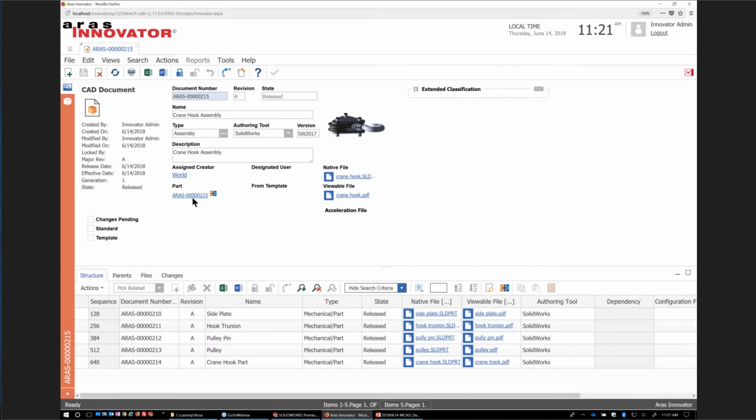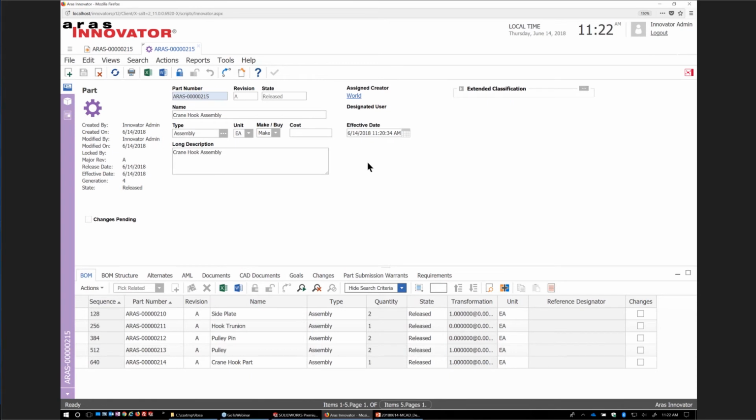So the connector is intelligent enough to understand that CAD-only specific items, such as skeleton, will be excluded and not be part of the BOM. This is important to mention because, especially for companies engaging in top-down design, they're using a lot of the CAD tools to capture design intent. The connector is intelligent enough to understand some of those design functions and only allow specific CAD structure to be put in, and exclude things like skeleton that do not belong inside of a BOM to be reported.